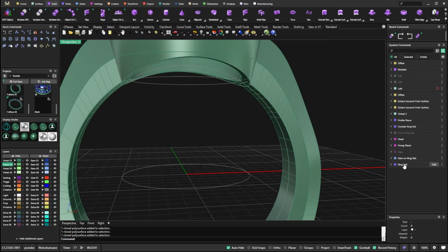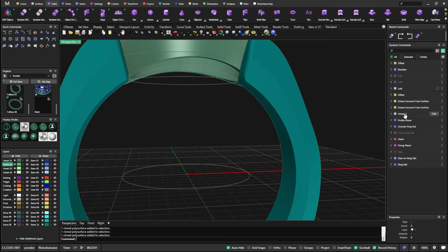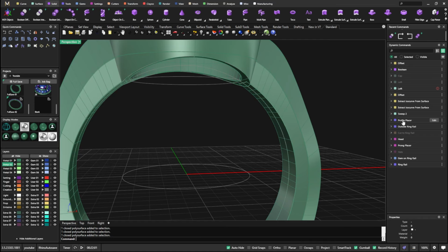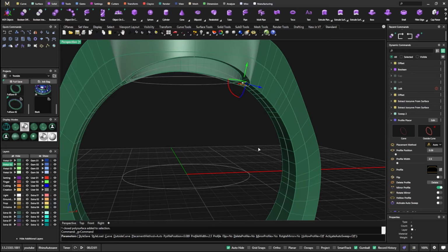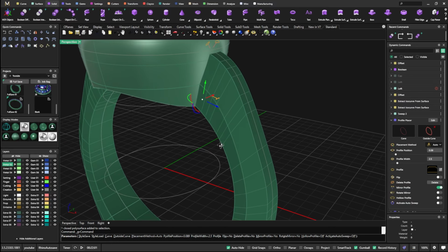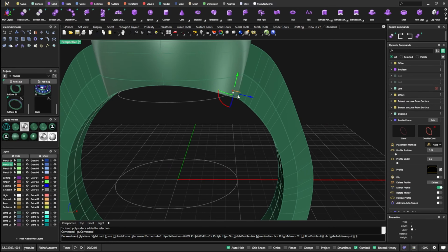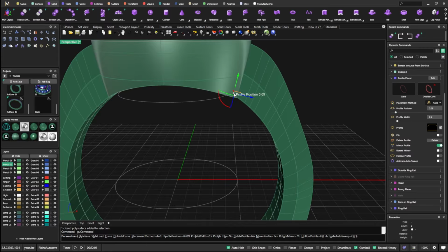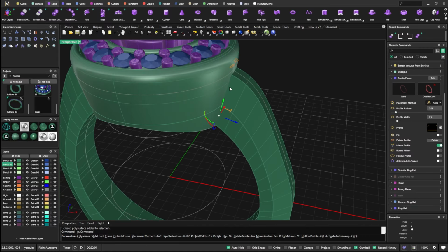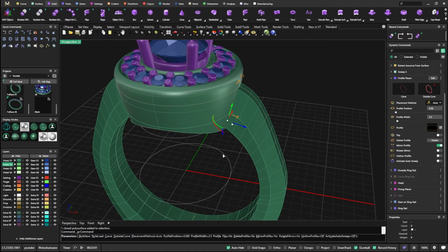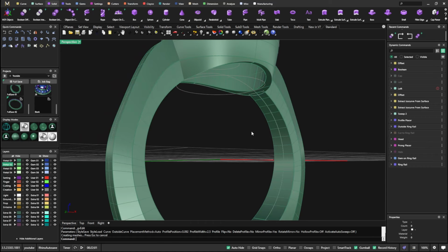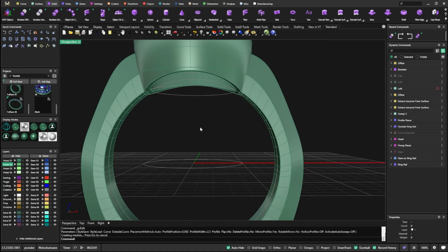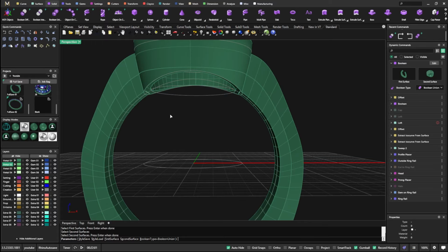Let's go to our, not our sweep, our profile placer here. Select there so we can get in here. And let's basically just drag this one back just a little bit. Still make sure that it's touching and everything. Maybe that was sharing a common area there. Not really sure. So let's try the Boolean union again. First surface, enter, second surface, enter, and there we go.